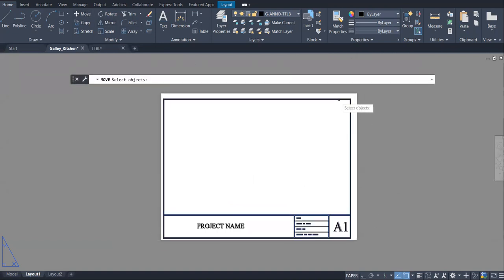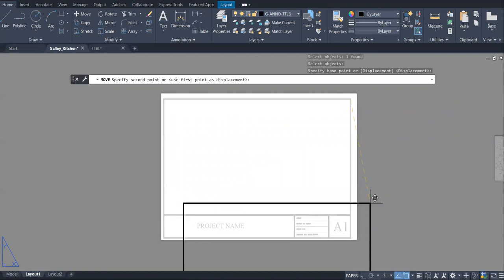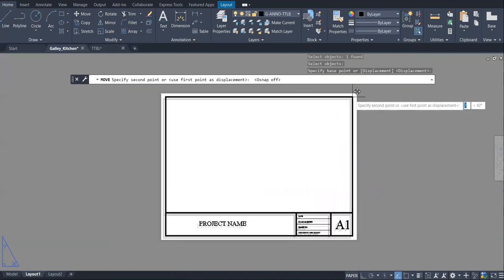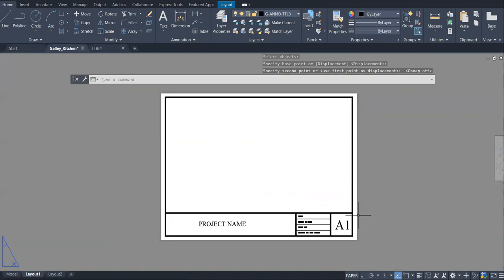One of the things that might also help me, if I click here, and then go here and turn off object snap, because sometimes it can snap to the margins of the sheet. So here it seems that we have done well in situating it almost in the middle of the sheet.